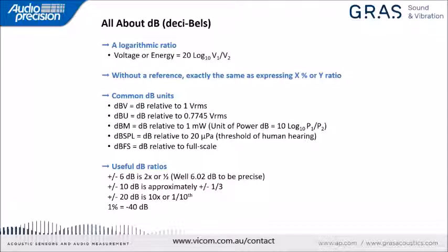And in that context, it's important to realize that unless it's understood, something like 20 dB by itself has no meaning. Saying something like that is no more sensible than saying 42% by itself. Decibels only mean something when a reference is provided.